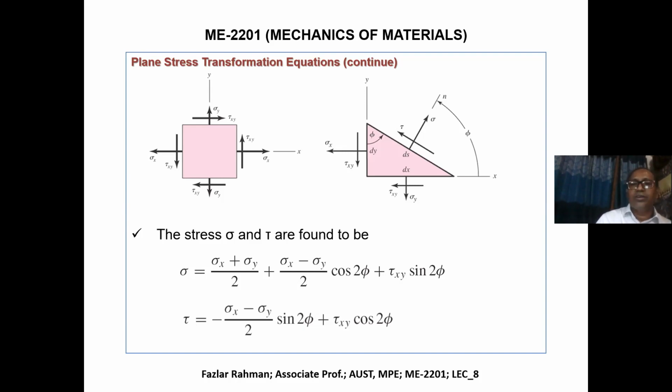You cannot do iteration. Each time you put a value, make a spreadsheet, you can figure it out, but mathematically we need to have a formula for which value sigma is maximum and tau is maximum. So for a cutting angle, say phi equal to, I'm just saying phi 9. Like you put phi equal to 10 degree, 5 degree, 18 degree, then 26, 22, and you are gradually increasing the angle.